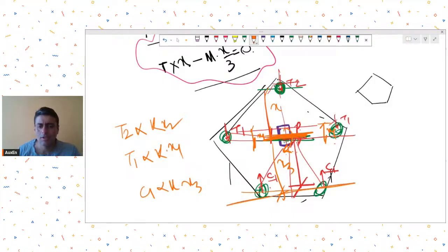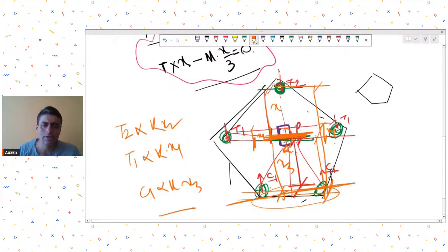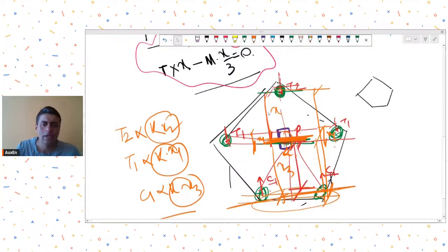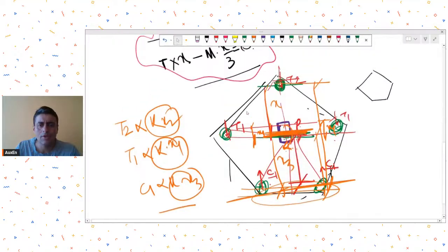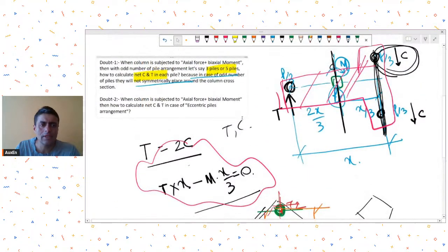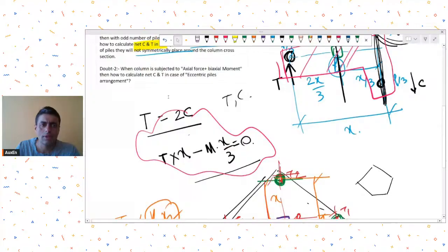and then about this axis, or about one of the center lines of the piles, I can take the moment equation, okay? So T2 into this distance plus 2T1 into this distance plus the moment shall be equal to 0 on this axis. So using that equation I can generate, and then I can replace these values over there to find out the k, and from there I can then find out the pile reactions. So this type of mathematical calculation you can do, or else if you are using some software like SAFE or STAAD, you could do it over there also.